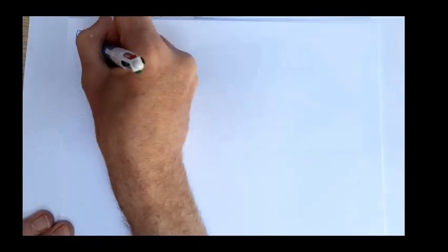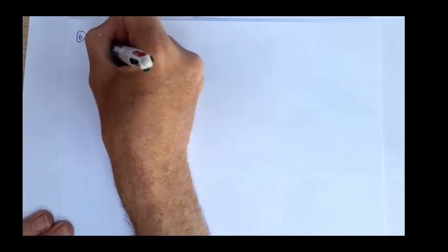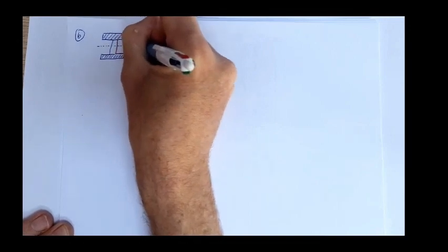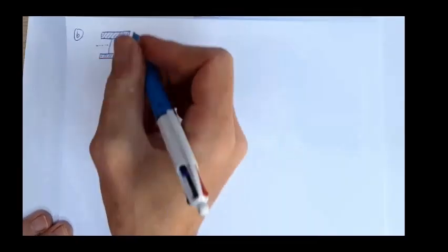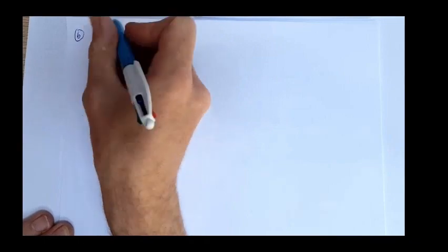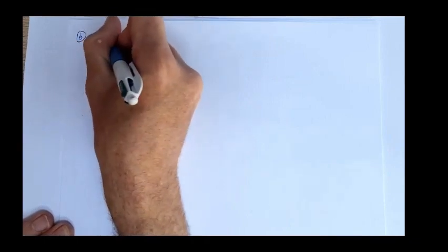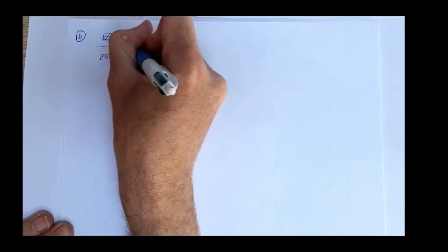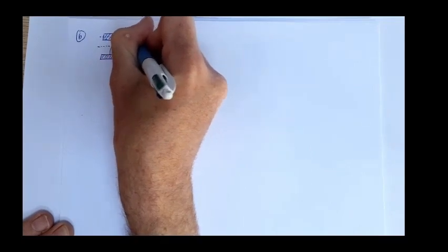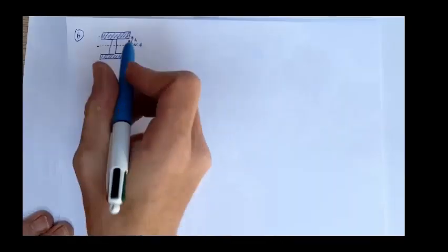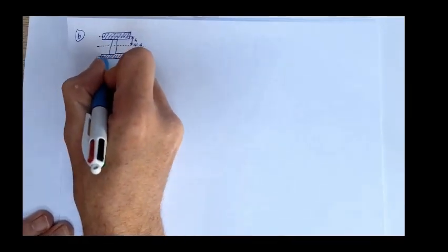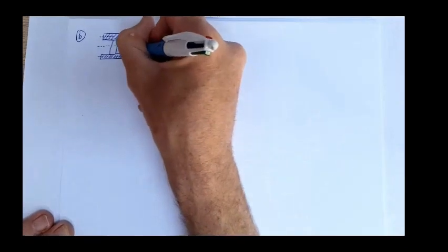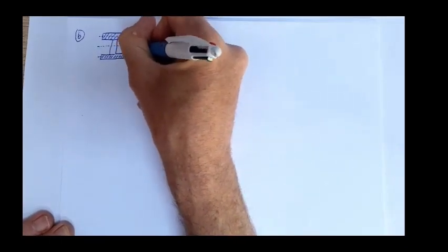Okay, my global neutral axis for my shape runs through this point here, and we can see this rectangle at the top has a local neutral axis which is offset by some distance. And the bottom rectangle is also offset by some distance, and actually that's the same distance, h.